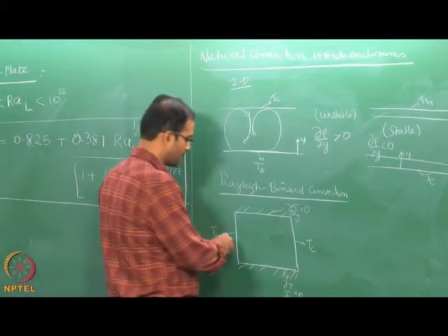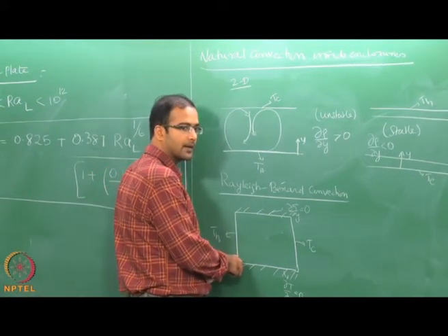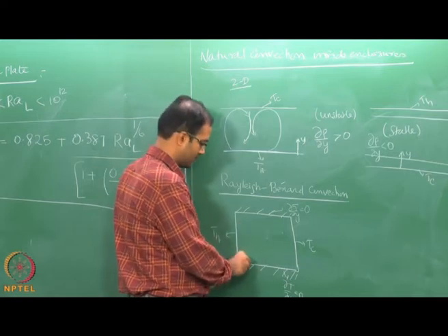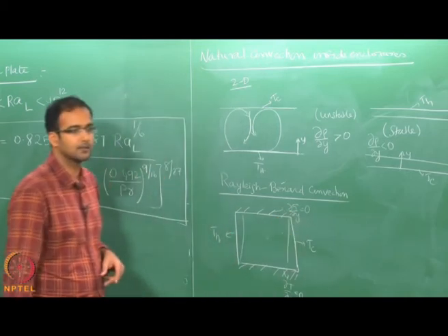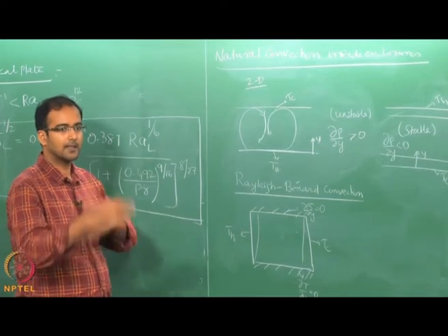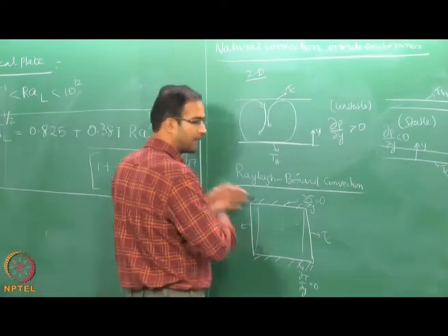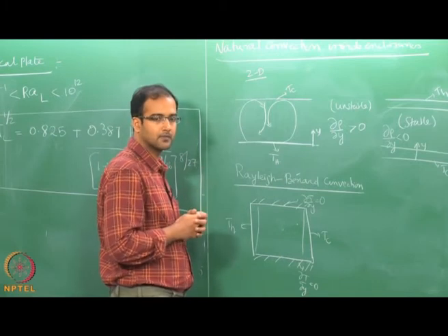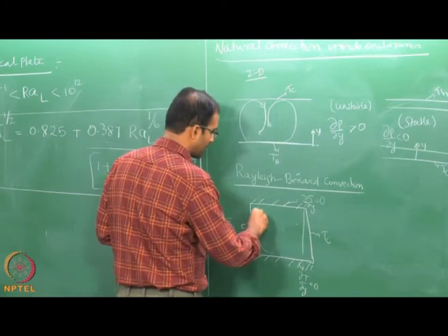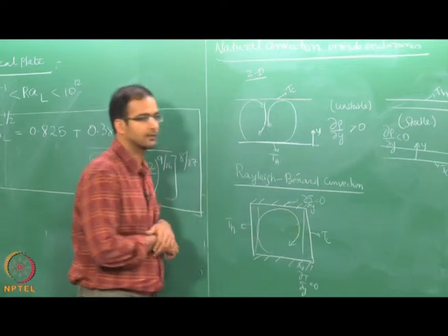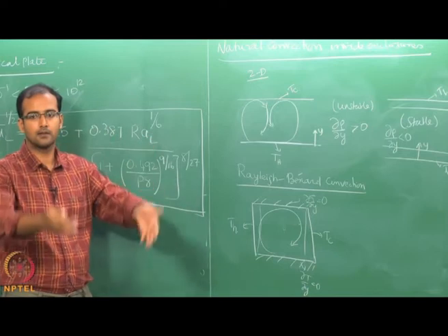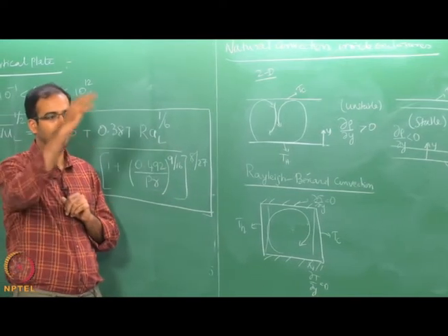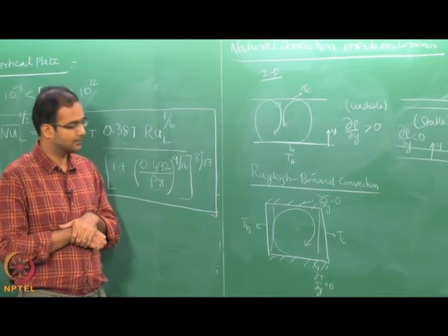Again, you will have a boundary layer which can actually grow, and again a boundary layer which will descend in this direction. So, what will happen together in an enclosure will be, the net effect will be a vorticity which will be driving a convection cell in this direction, the clockwise vortex. From the hot side it can only rise up and from the cold side it can descend down. So, you will be ending up with a clockwise vortex pattern.